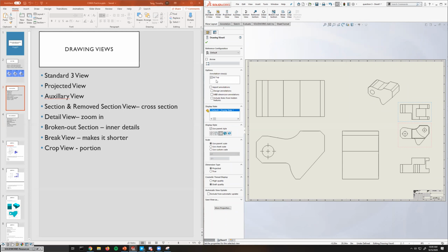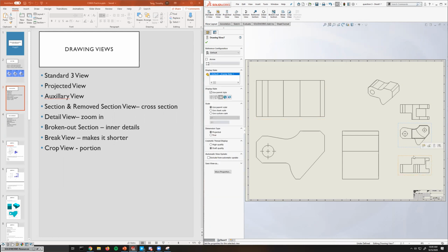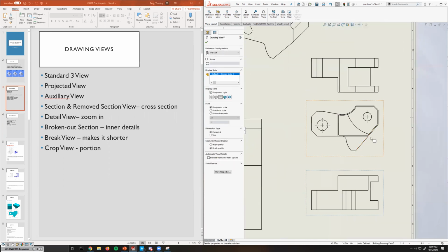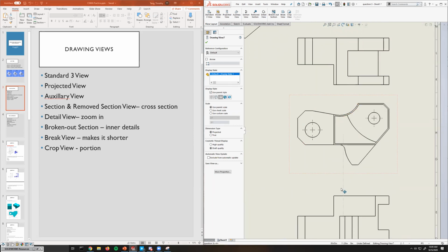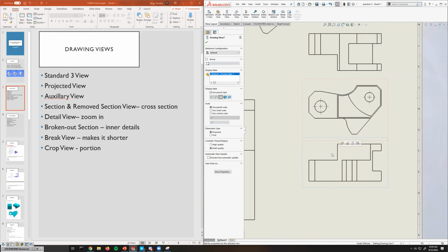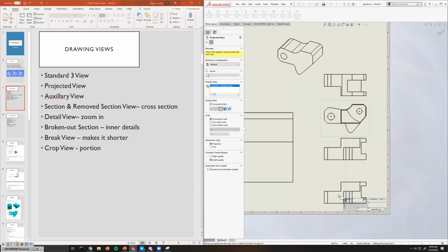Yeah, so if you can see on the left side, this says top view. And if you click on this one, it'll show you the front view. And then this one should be the bottom. So I'll zoom in a little bit so it's kind of easier for you guys to see. So if I drag this part, you can see like there's a dashed line in the middle. And what that's telling you is like, that's pretty much like the top or bottom view. So for example, if I go to projected view, depending on which side you pull that out to, it'll show you like different angles of that model.